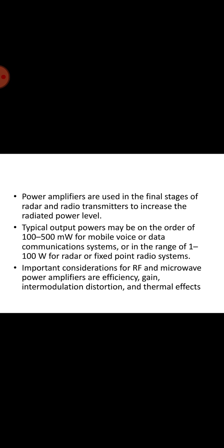But for high input powers, for example in the range of the 1 dB compression point or third order intercept point, transistors do not behave linearly. In this case, the impedances seen at the input and output of the transistor will depend upon the input power level, and this generally complicates the design of power amplifiers.